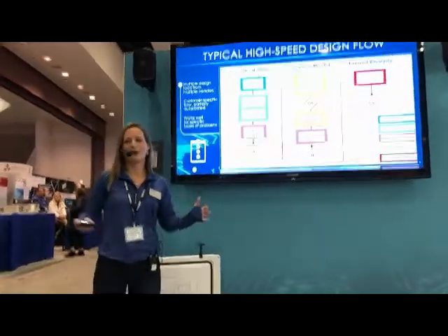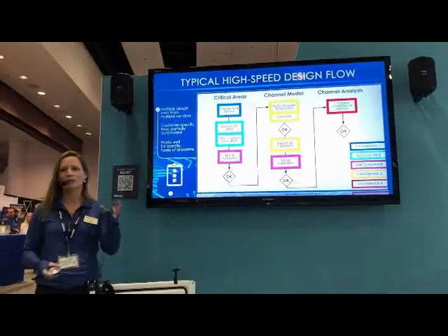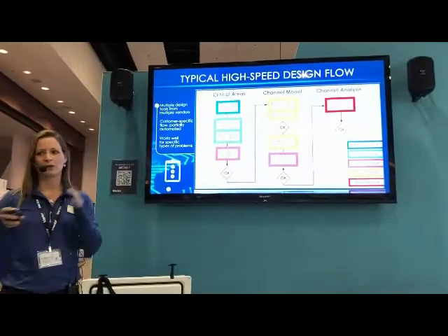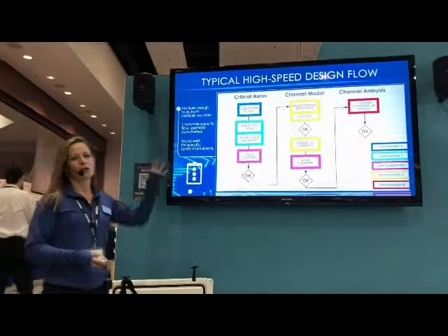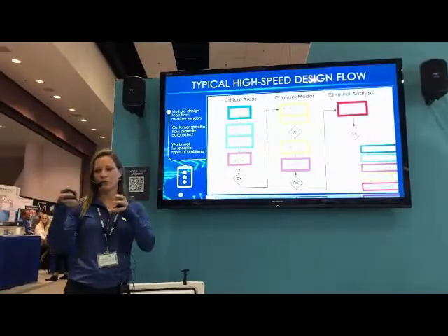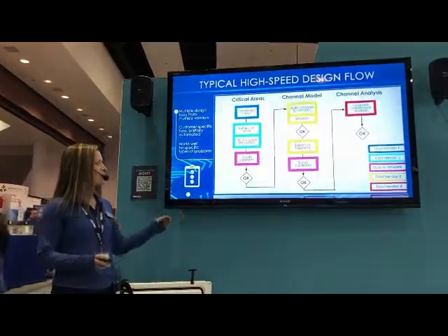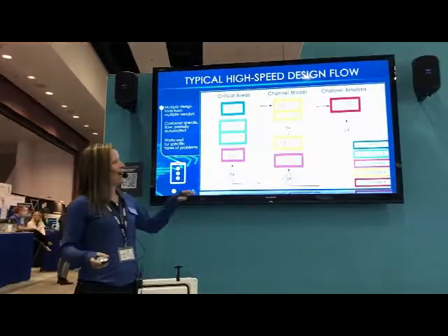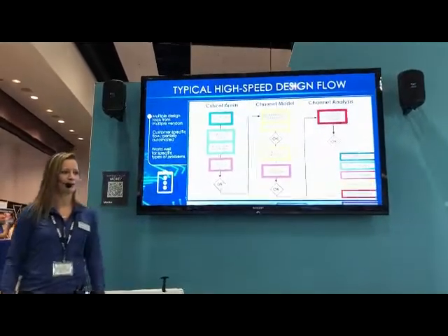However, because you don't have enough time, you're having to focus in on critical areas of the board. You're picking critical interfaces, and then even within those interfaces, you're having to parse that down into small regions such as breakout regions. Go through and analyze all of those separately, hopefully go into another tool, push all those blocks together to do transient analysis, and then probably extracting your end-to-end channel S parameters once again. And in the end, taking those to yet another tool for channel compliance analysis.